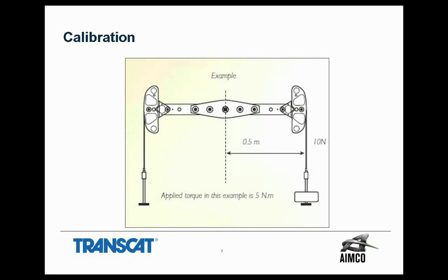In Europe, they pay a lot of attention to buoyancy compensation. It's pretty important when you're testing a torque transducer. It's not so important if you're testing a load cell, but it is important when you do torque. Obviously, temperature, humidity, and hysteresis are extremely important. Hysteresis: if you strain something clockwise, you need to take that strain out of that sensor shaft before you do it counterclockwise. So you have to pay attention to hysteresis.